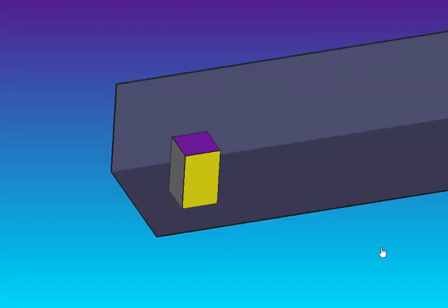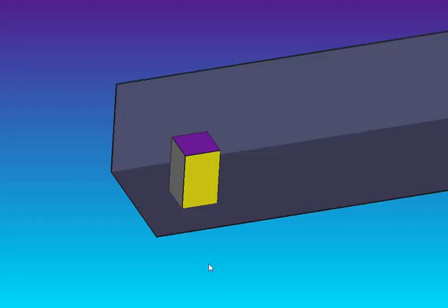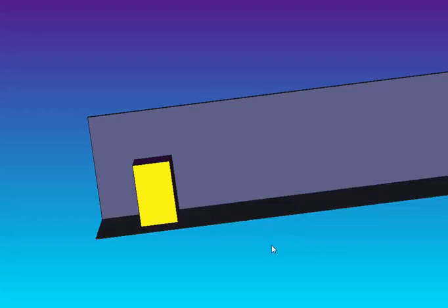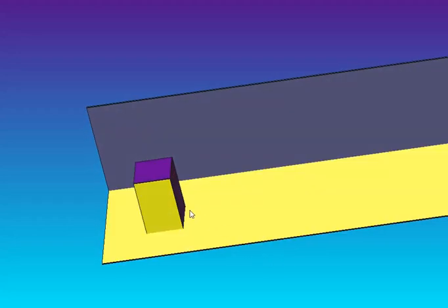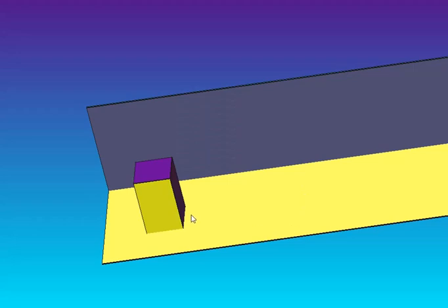Hello students, now we are going to understand the concept of projection of solids. As per the syllabus, we are going to keep the solids only on HP. In this case, you are going to rest the solid either on its base edges or base corner. Now, what we have kept for a square prism is resting it on its base.